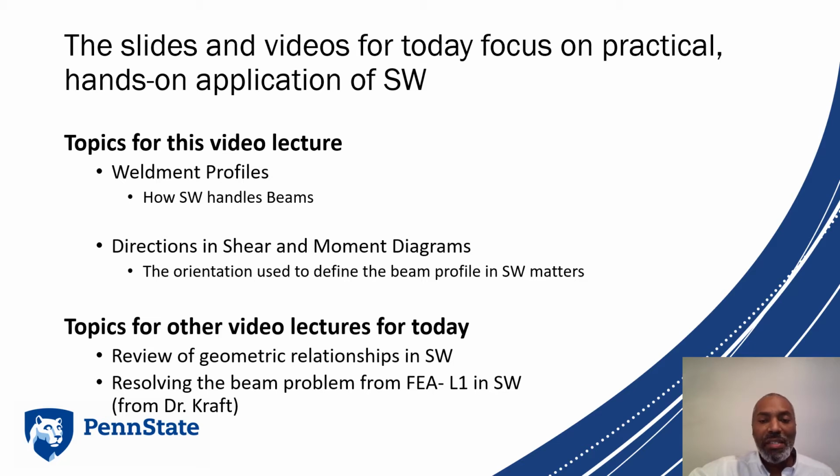Okay, so the slides and video for today focus on some practical hands-on applications of SolidWorks. As I said, the main topic of this lecture right here is weldment profiles, an overview, kind of high level of where they fit within the SolidWorks hierarchy and how you go about beginning to implement them. Also important is the direction of shear and moment within your weldment profile, because the direction that you define that profile in will affect the shear and the moment diagrams based on the directions of the forces and the moments within that beam itself. So you have to have those things all aligned.